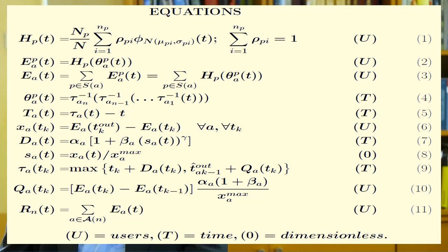Equation 7 is the BPR travel time function, which gives the link A travel time at time t in terms of the free travel time alpha_a, that is, when no other user uses the link, and the congestion parameters beta_a and gamma.